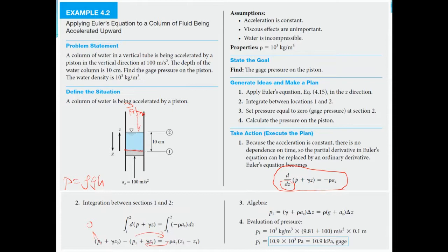we can bring this pressure here and bring these terms here. When we do that, P1 will be equal to, we'll still have gamma, then Z2 minus Z1, which is simply delta Z. P1 is just simplifying this one. Az is given, delta Z is given, so you just substitute and get your pressure, which is gauge above atmospheric. Which is gauge pressure.